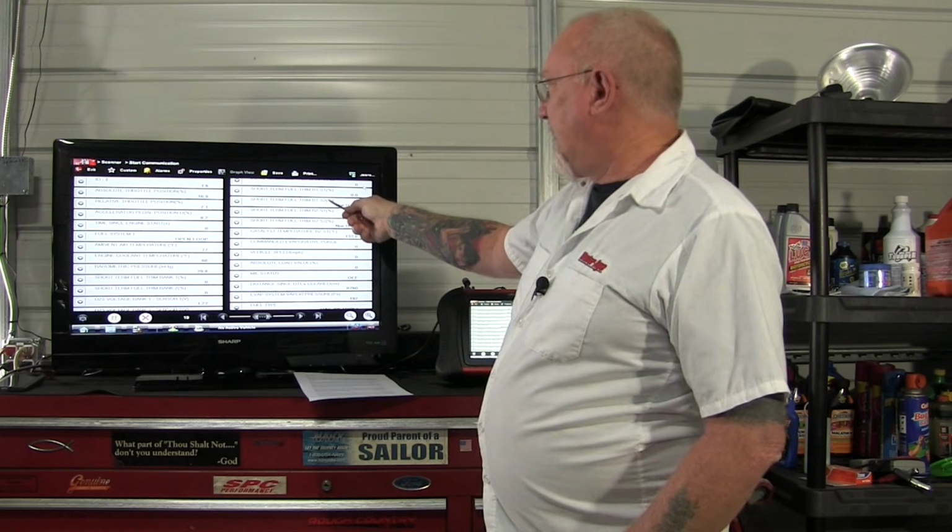Okay, how about short-term fuel trim bank 1 sensor 2? Okay, here's the number. And it's going down the list that way. So it can take a while, if you're looking for accurate current information, for that scan tool to populate all that information. Better pick the PIDs that you want to look at related to the problem that you're trying to diagnose.